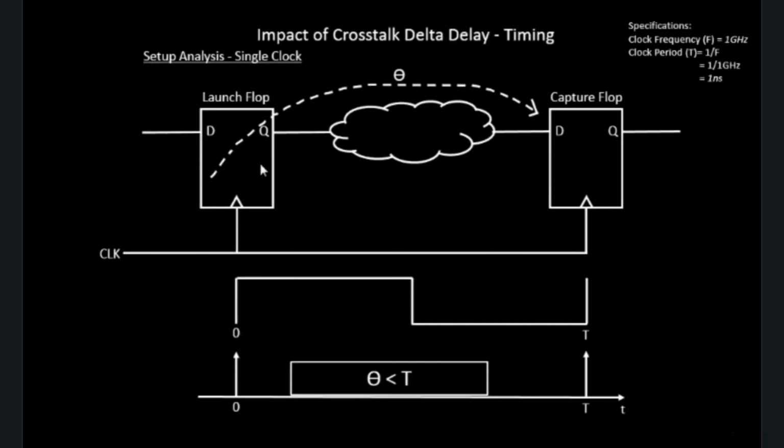Also we saw that this particular analysis was done with an ideal clock. By ideal clock we mean that there are no buffers. It is just as good as a zero wire load. These are not physical wires, and the clock tree is not built. We went with an ideal clock.